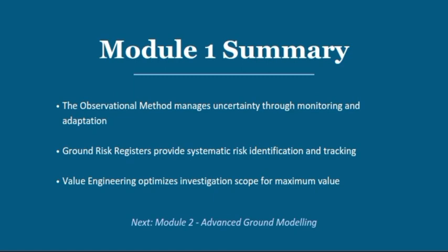Design a preliminary investigation strategy for a bridge crossing a river valley. Identify key geotechnical and hydrological risks. Prepare a simplified ground risk register. Explain how the observational method could be applied during construction.